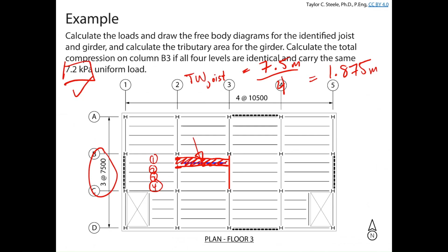And so if we go ahead and we try and set up what that problem looks like, we're going to have a simply supported beam. And just to remind everyone, the reason we're using a simply supported beam is because we're dealing with simple framing where the connections at the ends of the building don't transfer any moment. And so for connections that don't transfer moment, they only transfer shear, we can model that simply as a simply supported beam. Now, this is not exactly right, but it's close enough. It's a model that's going to give us the information that we need to design our structures to be safe.